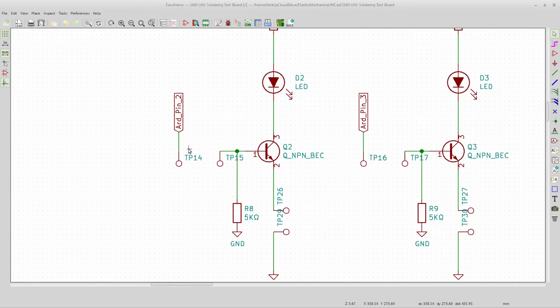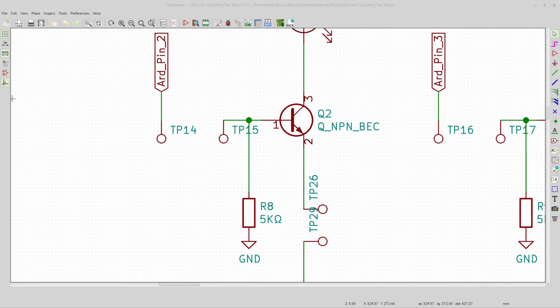Normally this circuit, let's say, is off, and then when you activate it, it goes up, so now it's 5 volts, and then you want to pull it down. Sometimes the circuit is predominantly on, so it's up at 5 volts, and every so often you turn it off. Well, in that case, you could have the same problem, but in reverse. So you might have this resistor going up, let's say, to hold it at 5 volts, and then you pull it down to ground every so often, and it will snap it right back up to 5 volts. Okay, so we have pull down and pull up resistors. So then that's what I wanted to tell you about the circuit before we get to actually soldering on the one on the board itself.